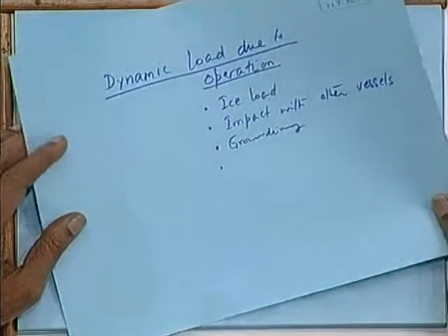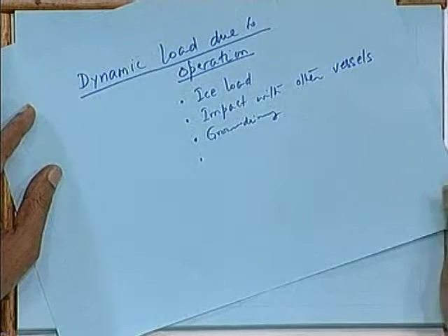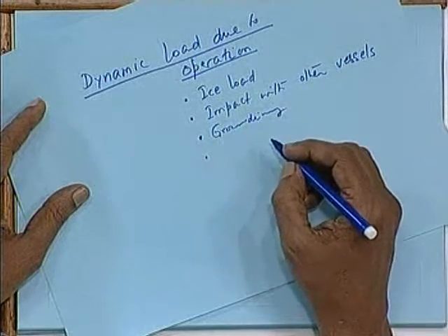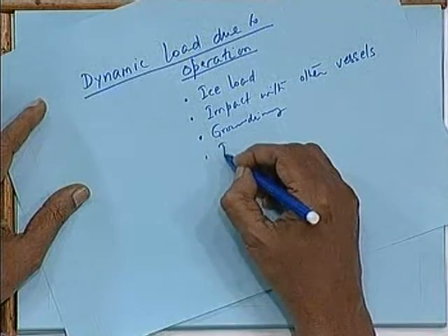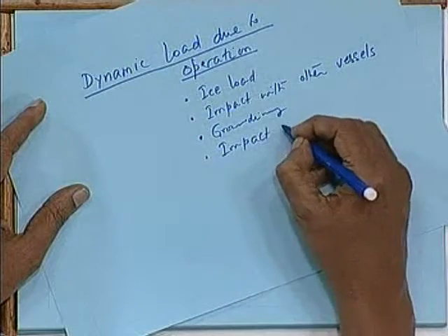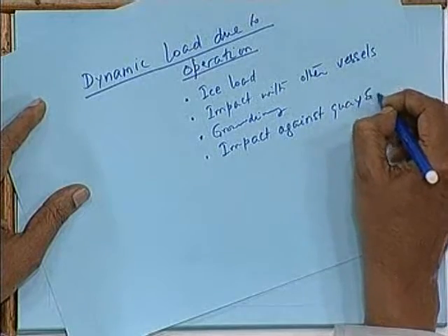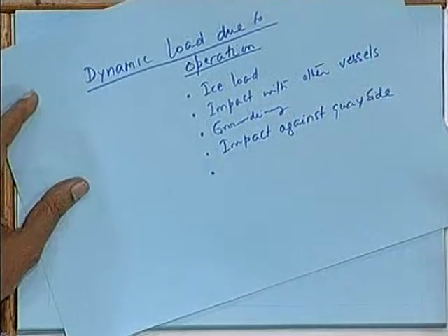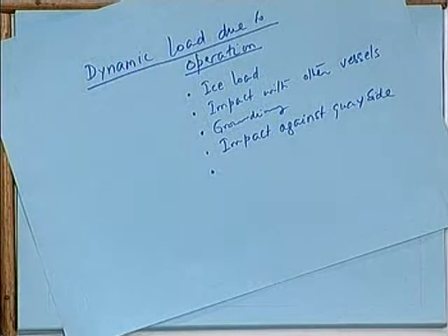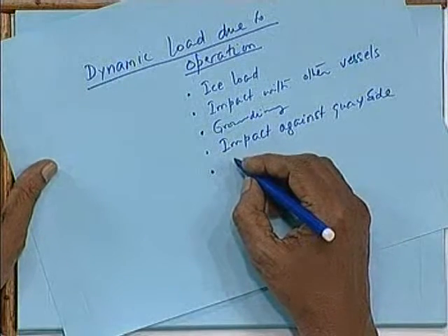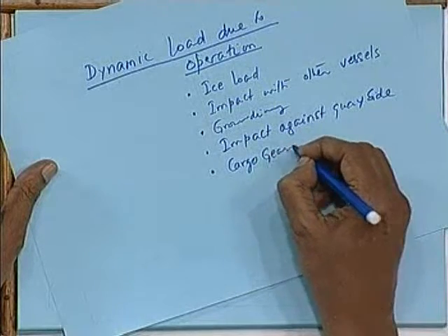Can we think of something which occurs due to loading and unloading operation? Along with, yes, impact against quayside. One loading which is pretty common, which stresses the vessel very much, typically in a bulk carrier, is cargo gear impact. Cargo gear operation and impact.